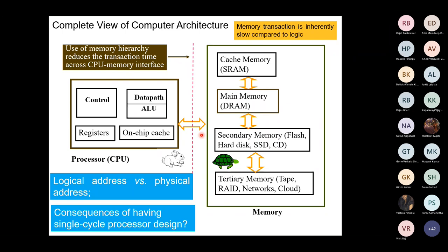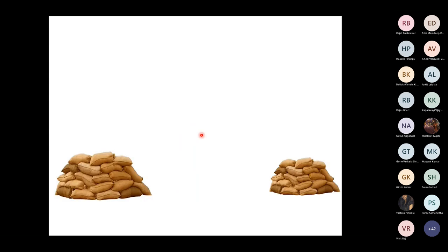So I'm talking about single cycle processor design. Then what should be my clock cycle time? The maximum possible time for an instruction to execute. Okay, so this is almost infeasible, isn't so? If you are lucky, if you find the instruction or data in the cache, fine, you just find them in one shot. But if not, you have to prepare yourself for the worst case as well, and therefore this is infeasible because you have to extend the clock cycle time very long.